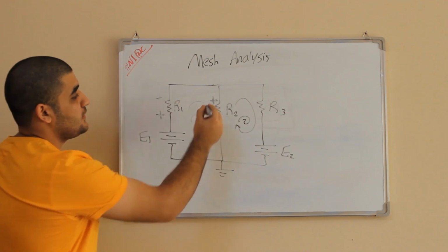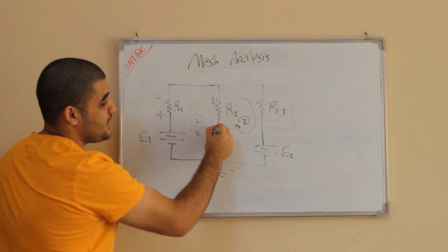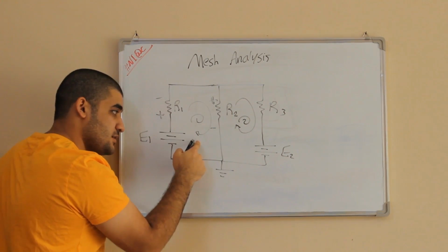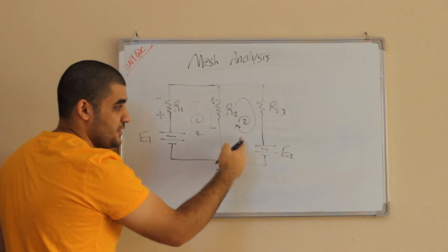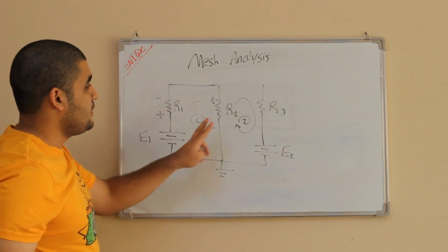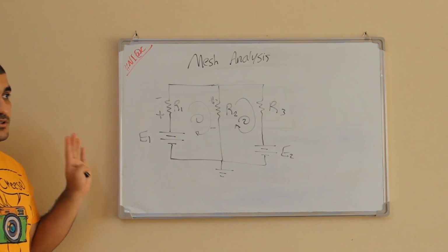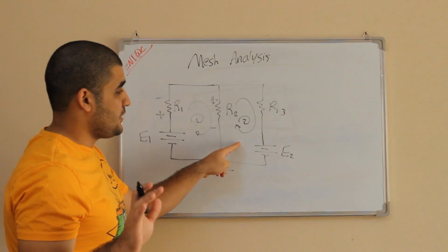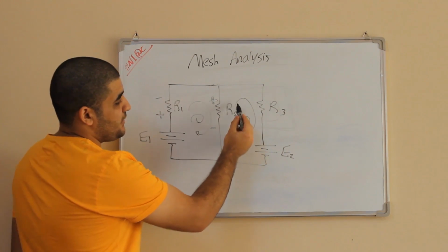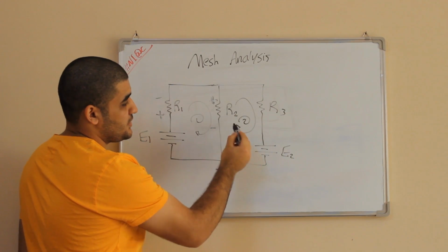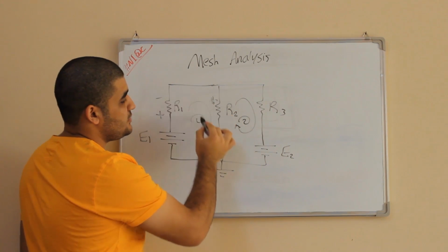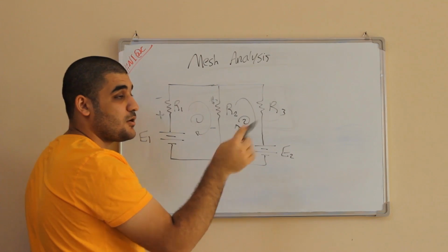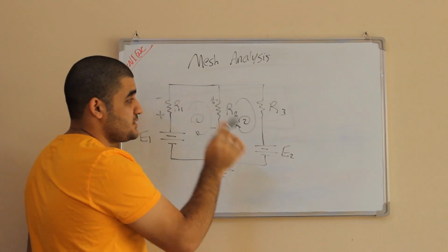So that's it. This is the plus, this is the minus, as I suppose that this current is greater in magnitude than this one. Now, the first loop is over. For the second one, I look at my assumed current. I don't play with this resistor because I already put the signs on it.